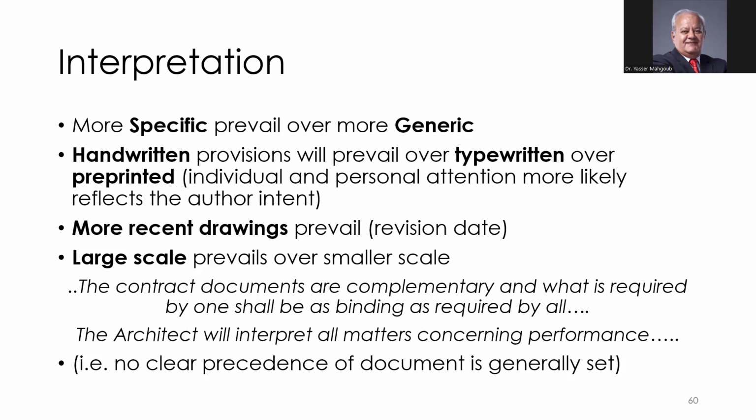So that's why in the title sheet we have to write the revision date. Who revised this drawing? And you have to make a cloud around the part that was revised, because you can have different versions of the same drawing, usually 5, 6, 7 during the construction. So the latest drawing prevails.